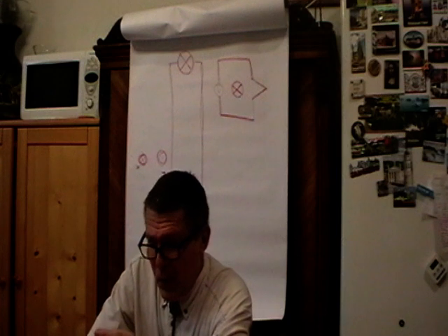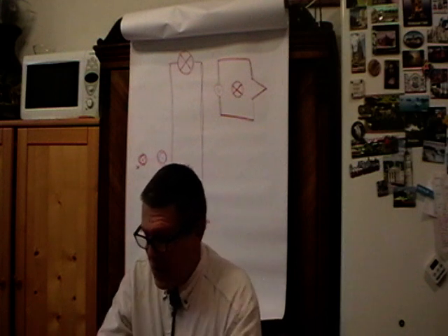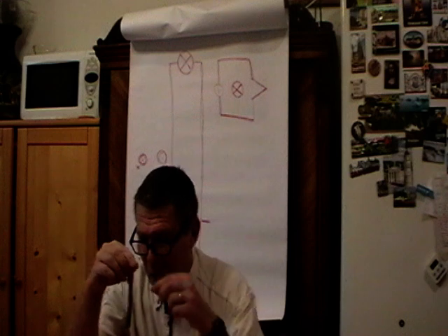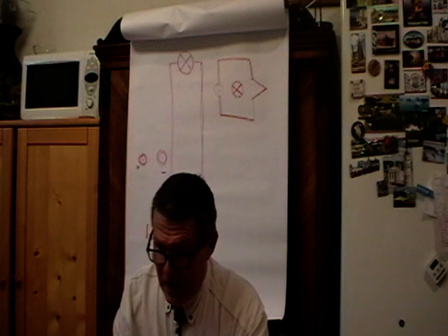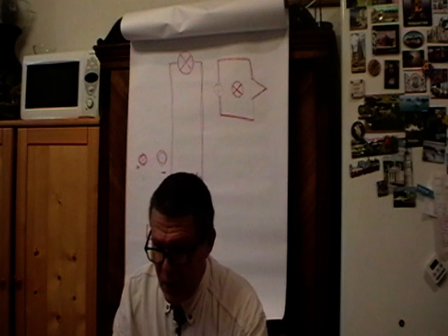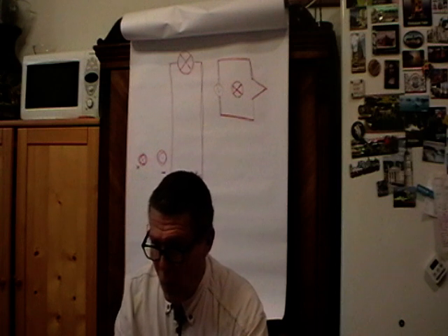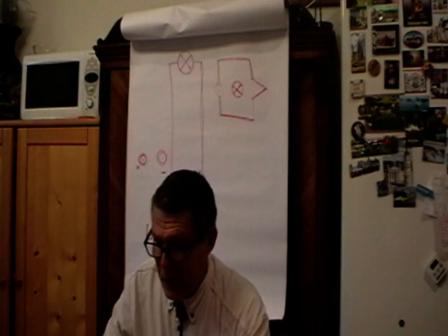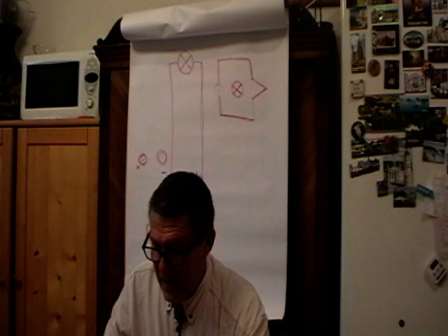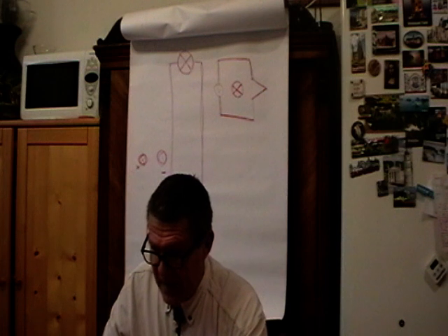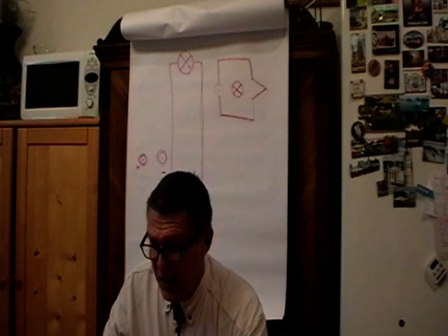So, if you have a small movement of an object, for example, if I would try to find out the dragging force of this pencil, and if it was magnetic, I could use a virtual work approach in that manner that I would calculate the energy of that arrangement with the pencil at one point, and then I will slightly move the pencil and examine whether there is an increase or decrease in the energy of the field.